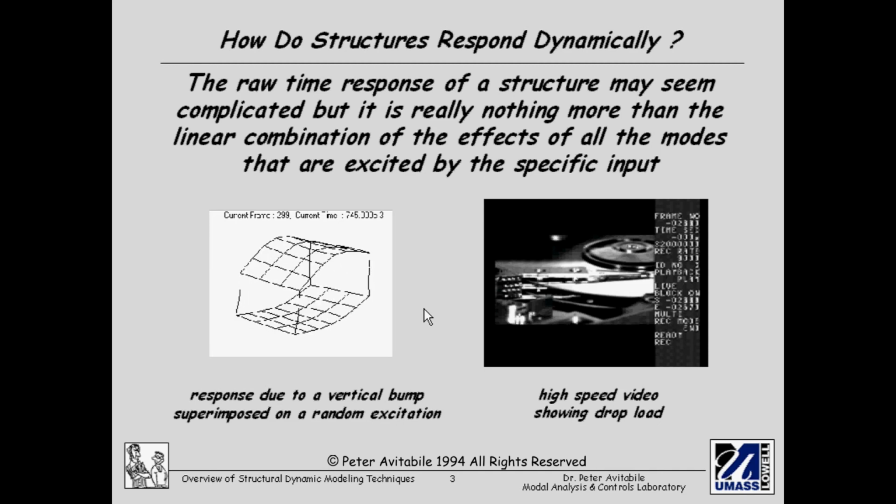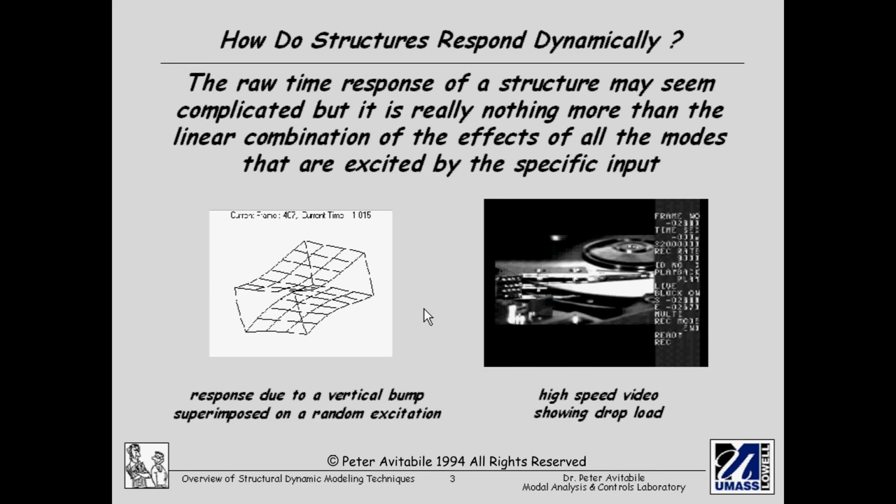Now this is the physical response of the system due to the applied load. In order to really understand how this structure behaves, we need to understand the underlying dynamic characteristics defined by the frequencies and mode shapes to understand how much of the response is dominated by which particular structural dynamic characteristics. So if we see the response right now, you'll notice that you start to see some higher order modes, especially in the upper plate and the lower plate, and you'll see what looks like a traveling wave. It's really just a combination of many of the modes of the system, but there are higher order modes that are included in that response.